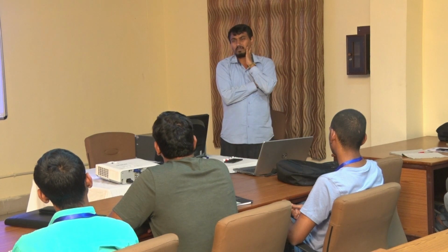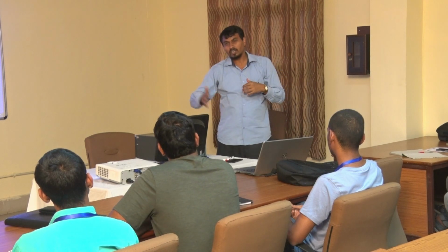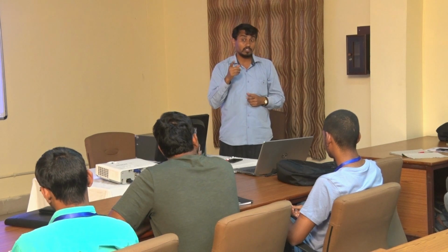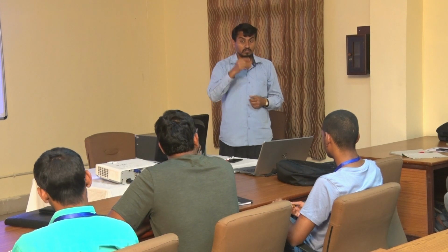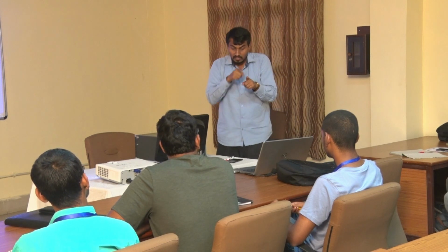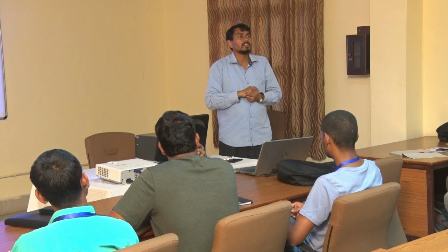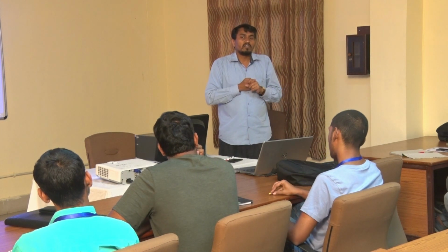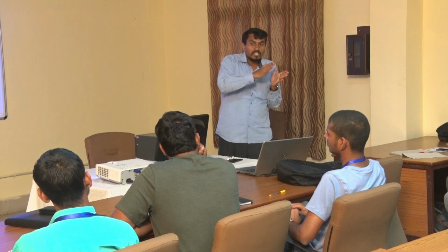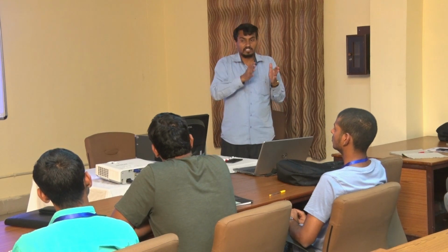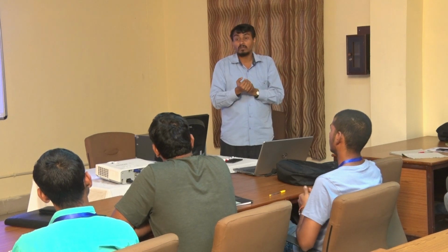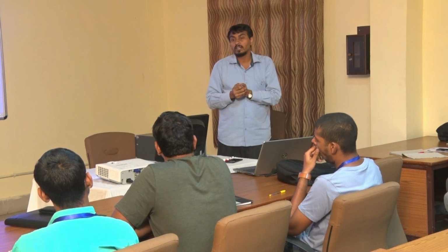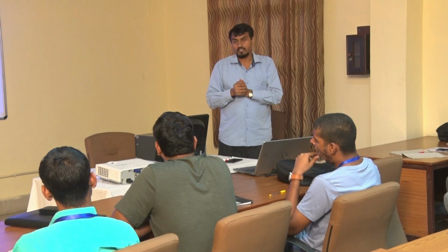Oh, it is very difficult because local failure is continuously going to happen. So the geosynthetic grid, of course, the material the grid is made of is also a very important parameter. What is the grid size you are going to take care of? So we can do numerical modeling before installing this kind of geosynthetic grid on the slope, on the loose material. We can test it and we can conclude something about the future prospect of using this geogrid for the possible stabilization of the downslope. We can do that. We have that.